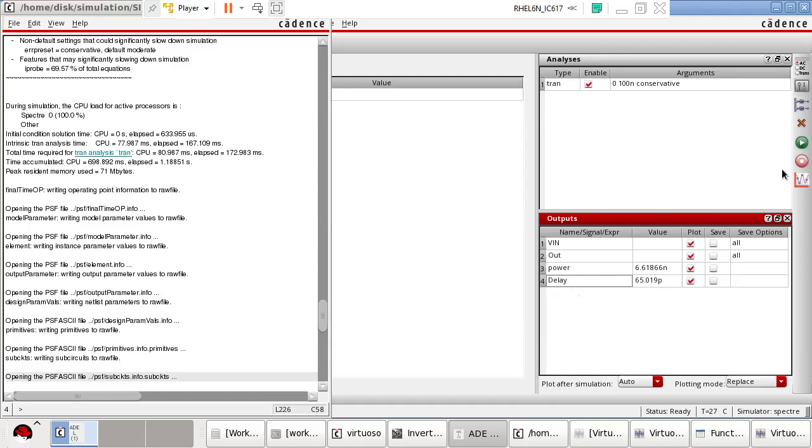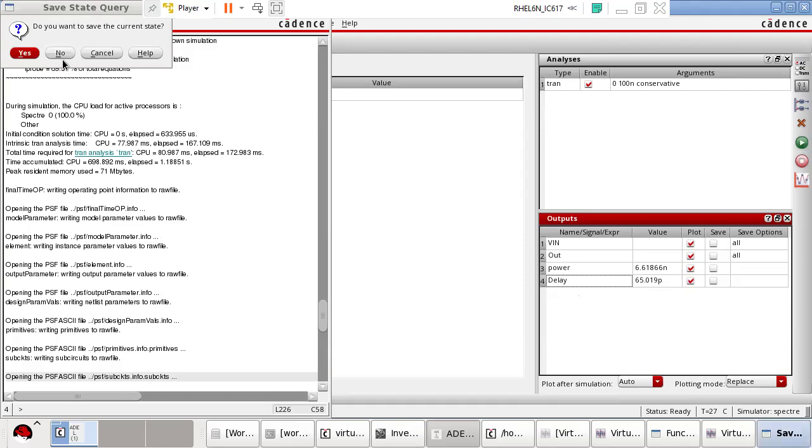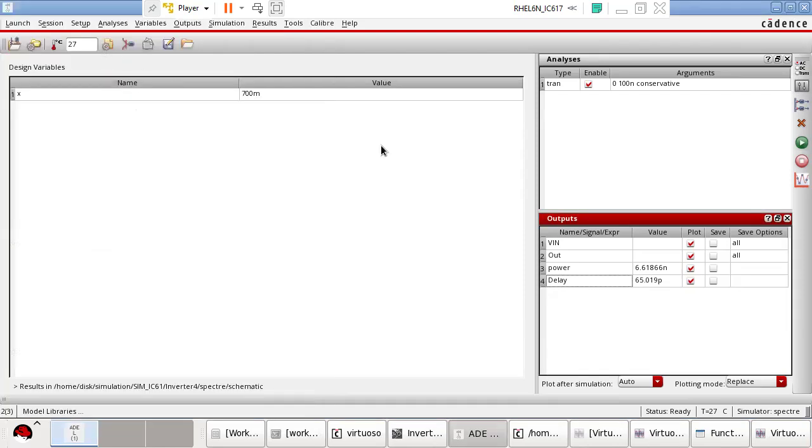What is the advantage of this technique? That this technique does not call for adding many transistors. It adds only one transistor in series as a stack, and one transistor as a sleep. This technique has another advantage: you can implement stack and sleep separately also, depending on the choice of your circuit. But I again say that please take it with a pinch of salt.